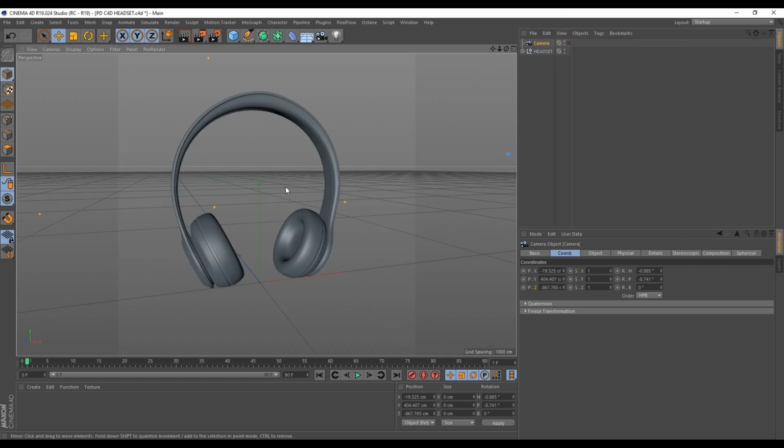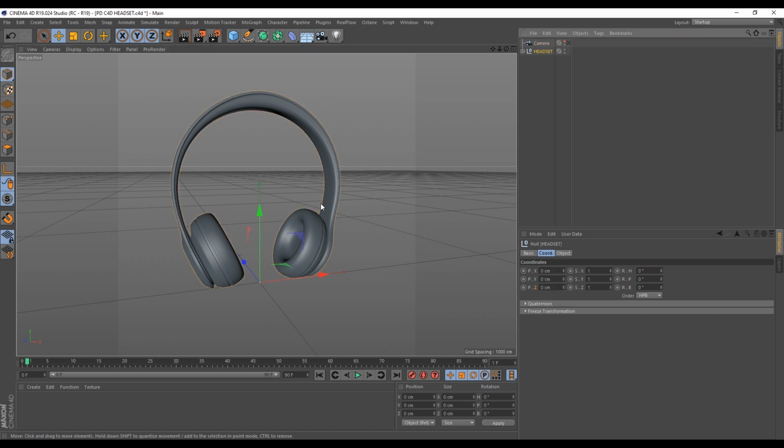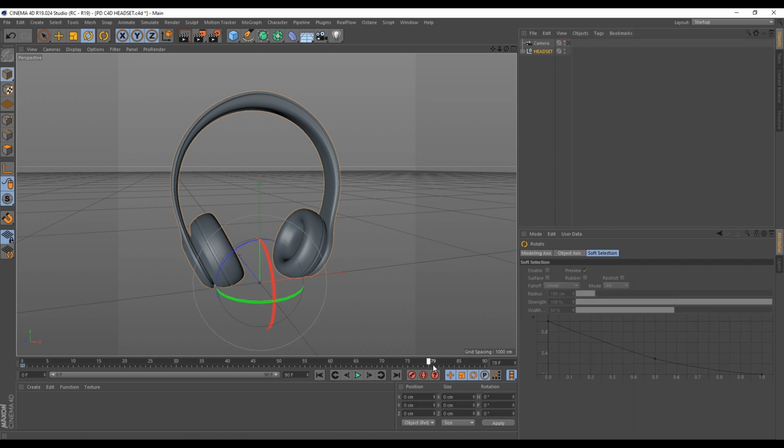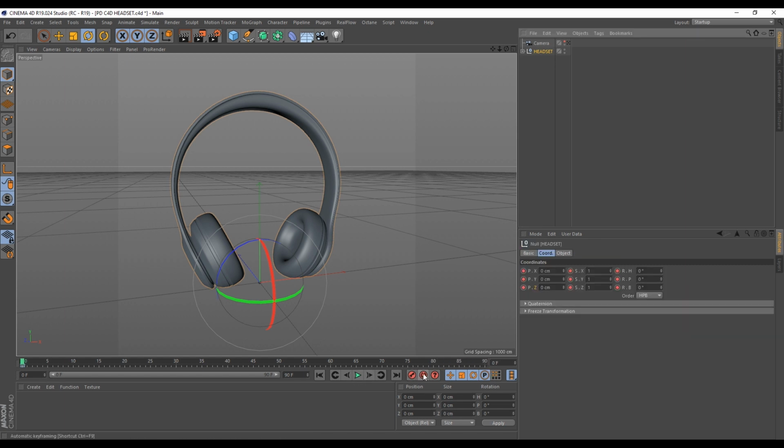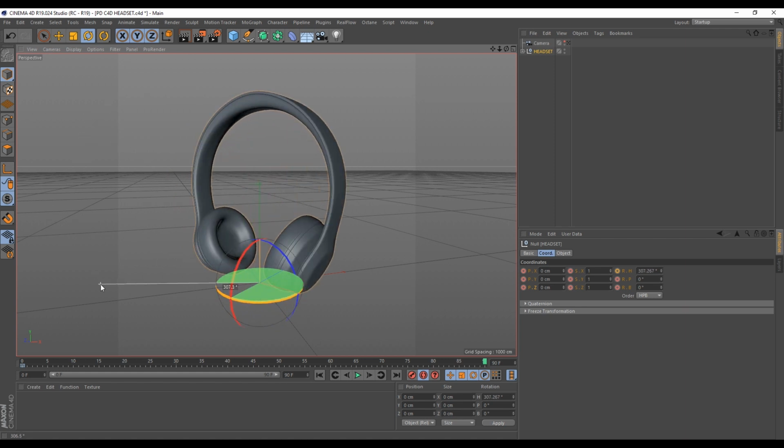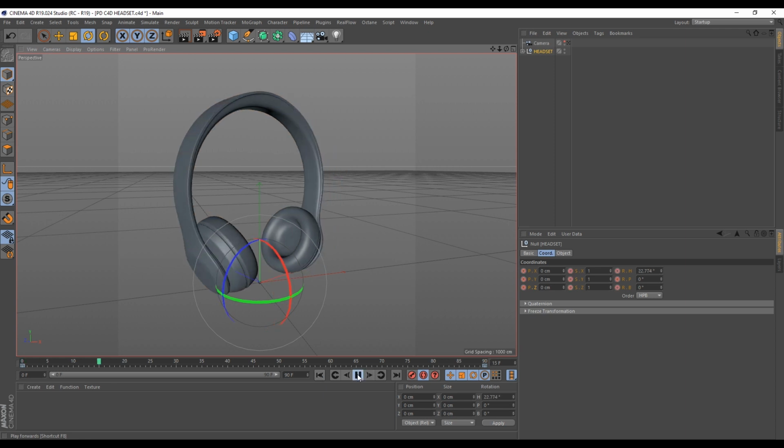So now let's animate this headset. We want to animate the rotation of the headset. So once I select this headset, we can use the same technique we used before, and we can also use our auto key in here. So I'll go to frame 0 and I'll just record everything, the position, scale, and rotation, as you can see here. I'll switch to my rotation tool. I'll go to frame 90. Then here I'll check auto keying so that the movement we'll make will be recorded. I'll go to frame 90 here. Then I'll just rotate this object this way. And maybe I'll stop here. So as you can see, a keyframe has been added at frame 90 and the rotation here has been recorded. So if we go back to frame 0 and I just play this, this is what we should have.